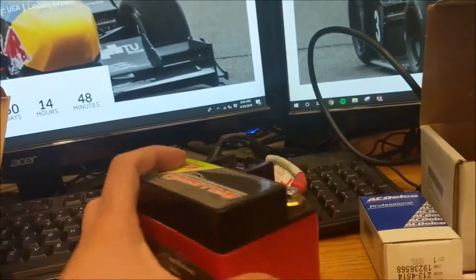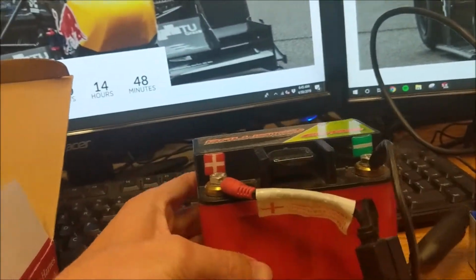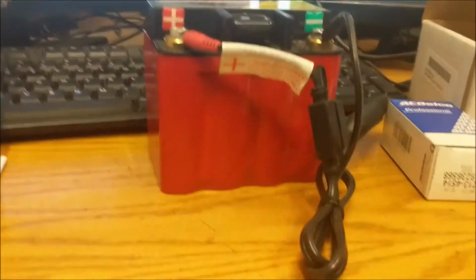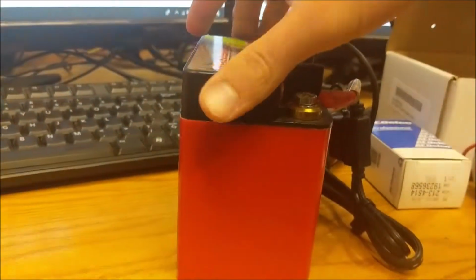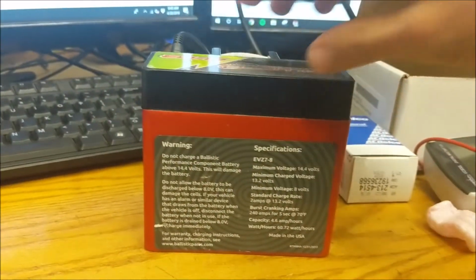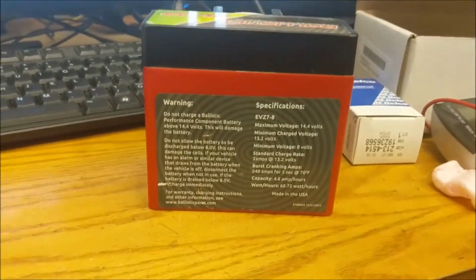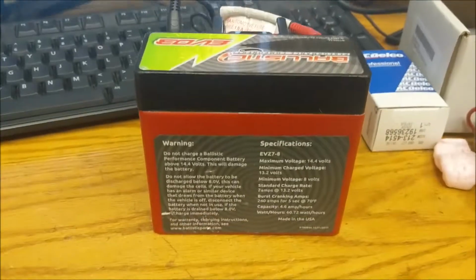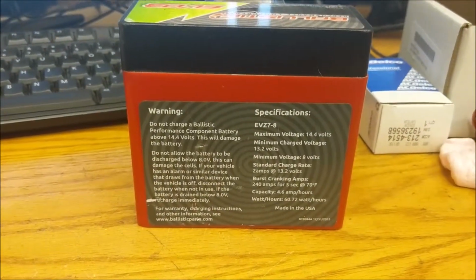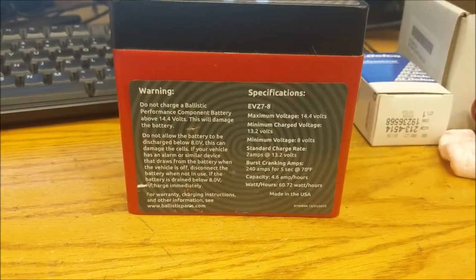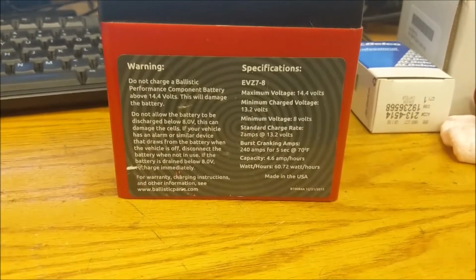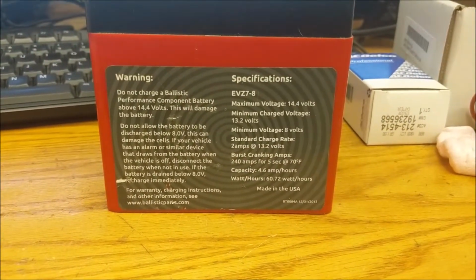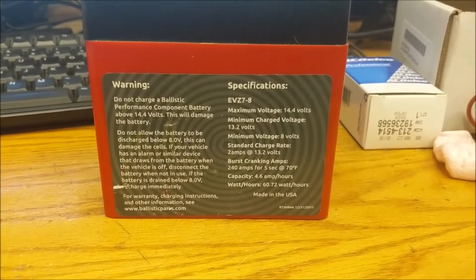Using a lithium-ion battery, a huge issue is catastrophic failure. If a battery is abused, discharged and recharged too much at a very high rate, then the battery may have a catastrophic failure. If a battery is overcharged, then it will damage the battery. Furthermore, if the battery is drained below 8 volts, the battery will also be damaged.